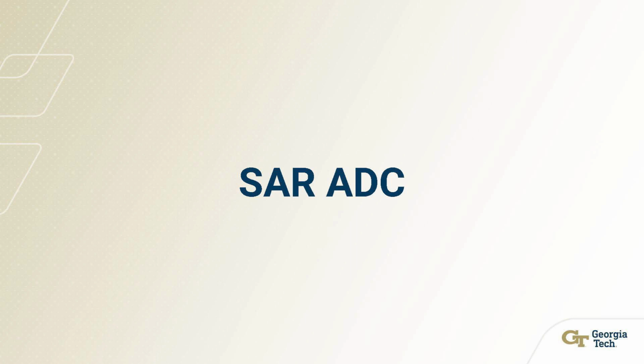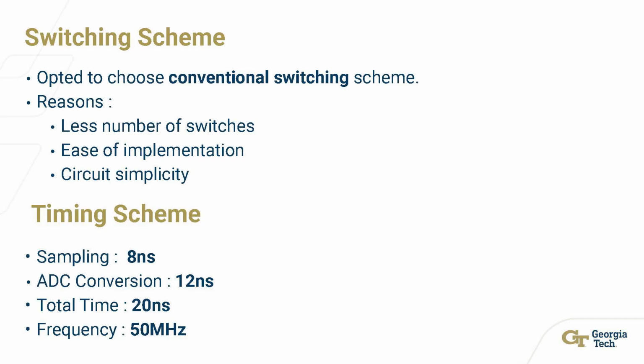Now we will look into the SAR ADC design. We opted to choose the conventional switching scheme as opposed to the VCM based switching scheme, and the reason for that is because in this scheme we will have a lesser number of switches. It is also very easy to implement, and the circuit is also very simple.